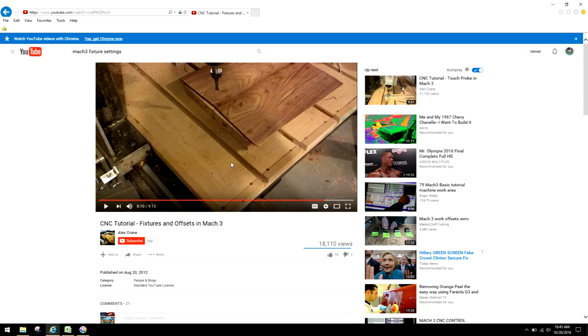It doesn't make sense, because here's the thing, guys, whether you use a switch or you use soft limits, once again, I don't recommend switches. I always go with soft limits. They never fail. If you're using that method and you're machining from this location, the thing to keep in mind is eventually, maybe not on the first job, but eventually another job, unless you're doing the exact same job every single time, and those are the guys that'll get away with using a switch, you're going to want to move your actual home position. You might home your machine here to say, oh, I'm at 0, if that number means anything, that arbitrary number. Otherwise, you're going to move it to where it's more applicable to what you're actually cutting. So just keep that in mind.